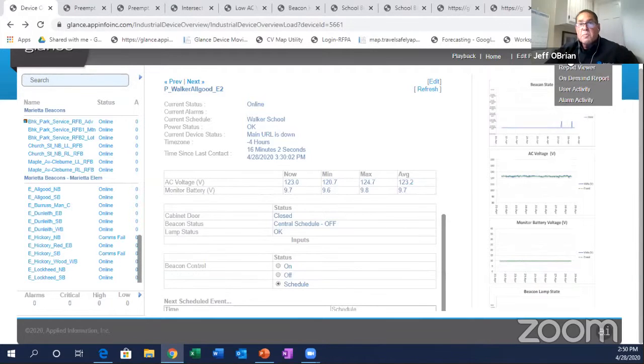So there's a specific piece of data we're looking for, which Chris indicated, the SPAT, the signal phase and timing data. It's not present. So we can distinguish that, yeah, we're getting everything else, getting what we're supposed to be getting with the exception of the SPAT. So it gives us the ability to designate that as a no SPAT. So it gives us very specific information. And that again goes back to being able to set that up on the controller to issue that SPAT detail to our device. Good question.